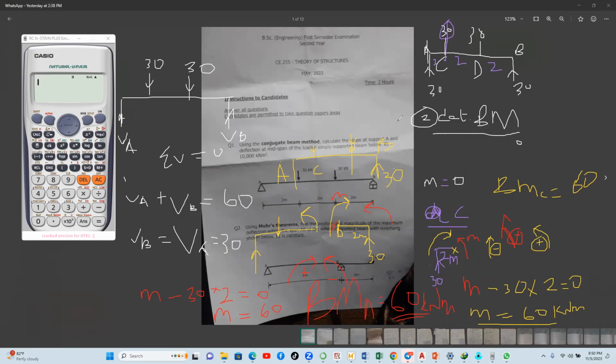So the bending moment at B, at this point, I said you cut, there will be nothing there to the right, but you have this to the left. And I said you choose only one direction, so it really doesn't matter which side you choose. So when you choose to the right, you are getting no moment. So your moment here is 0.